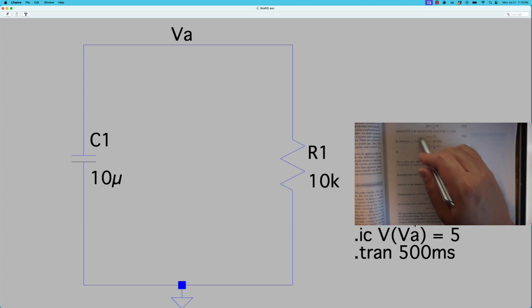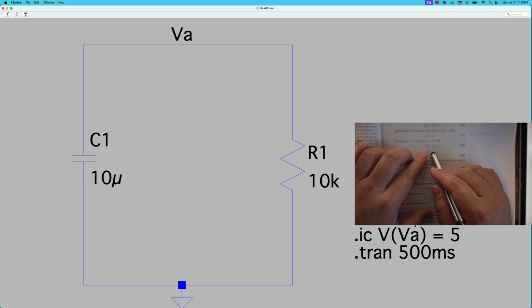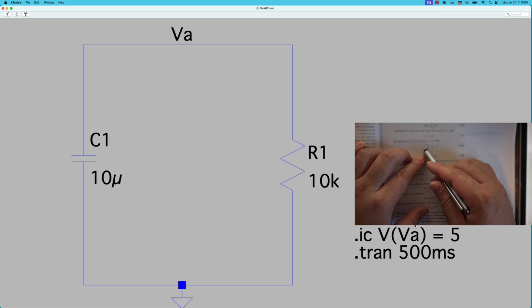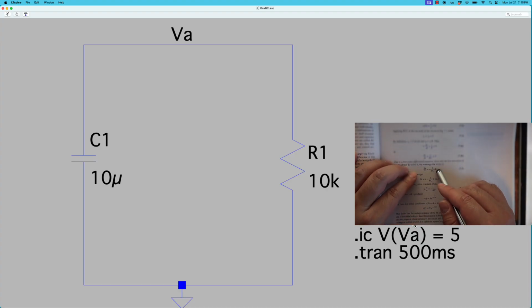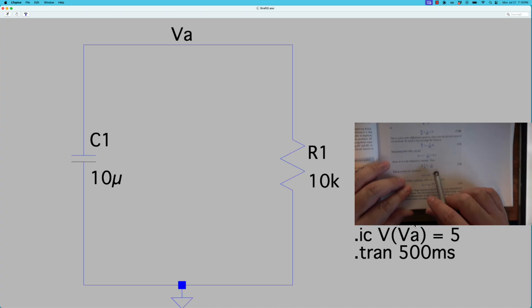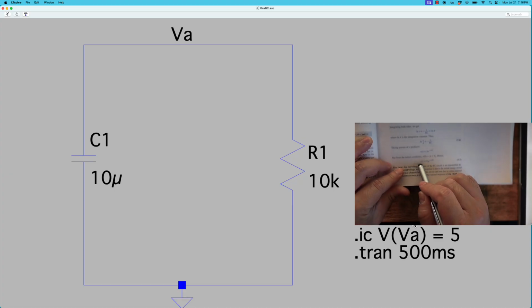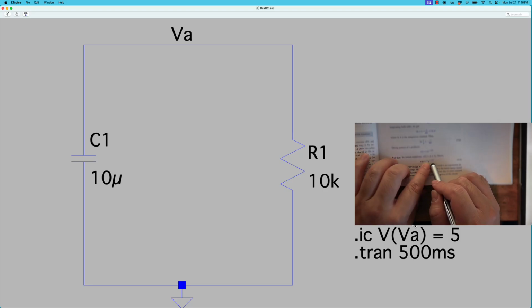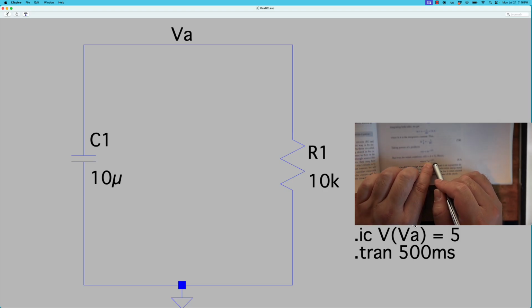And then we can work backwards to integrate or differentiate, to find the rate of change or to find the area under the curve, which is how much voltage has been dissipated over time. And then at the end we see V. This is with the initial condition of V sub 0. V of t is equal to V sub 0, our initial condition, times e to the negative t over RC.